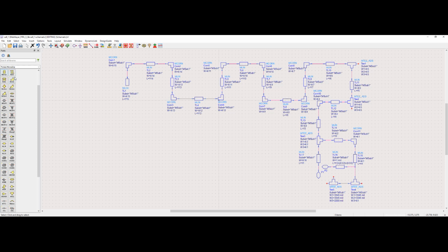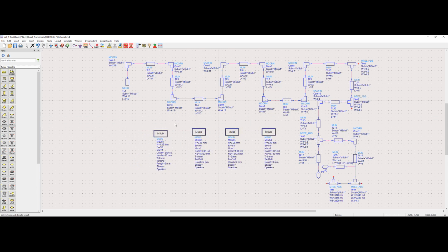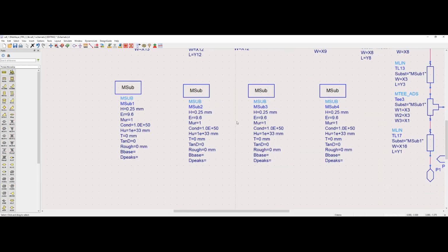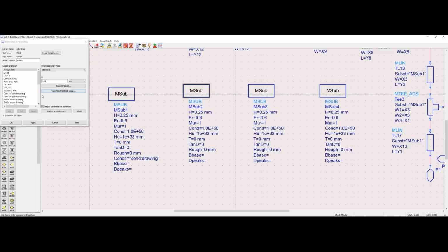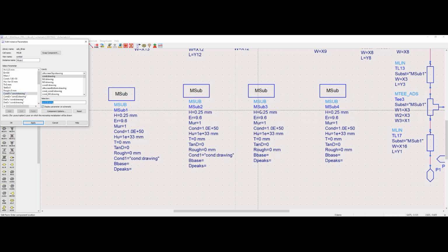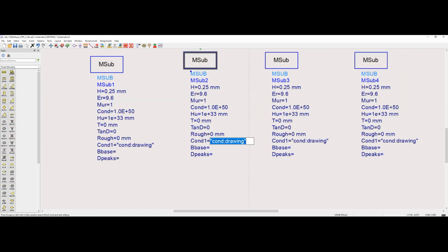We have completed the insertion of parameters to the appropriate microstrip components. Next, MSUP is inserted to define the layers of the PCB. This is a 4-layer rigid PCB with the antenna located on the second layer. After inserting MSUP, enable CON1 in all MSUP because that's where the layer is defined. CON is our top layer, followed by M2, the second layer. Next is M3, the third layer, and finally CON2, the bottom layer. These layers are defined in order from MSUP1 to MSUP4.